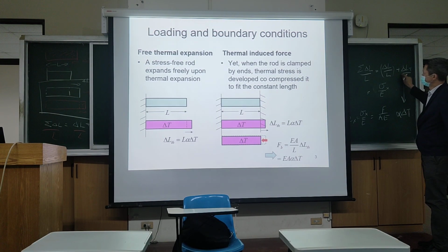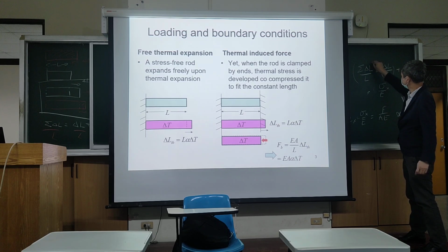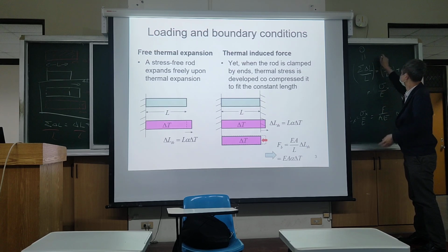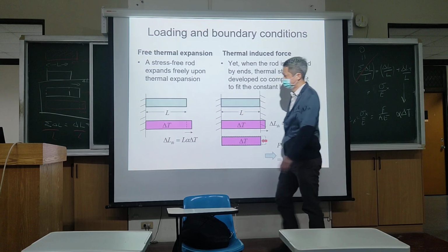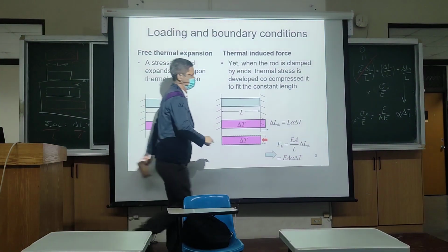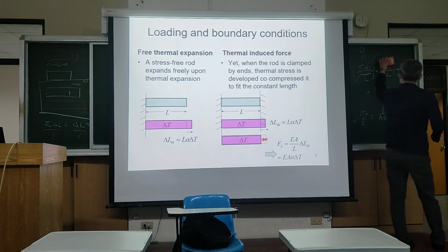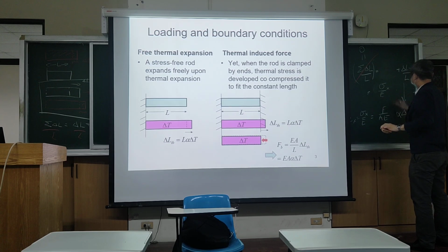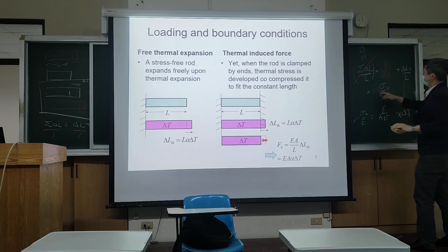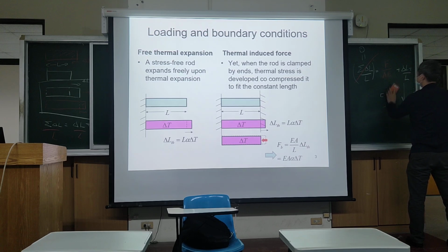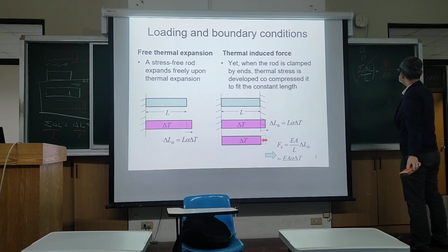So you see here, if the total strain is 0, okay? So meaning you need to induce certain force, okay? This term can then be written as the block force divided by AE. If the left side is 0, okay, then I should induce a block force.